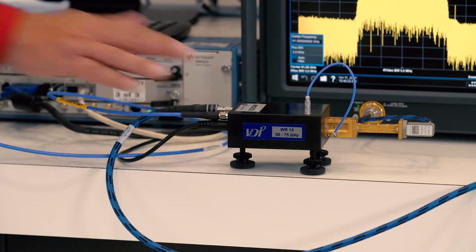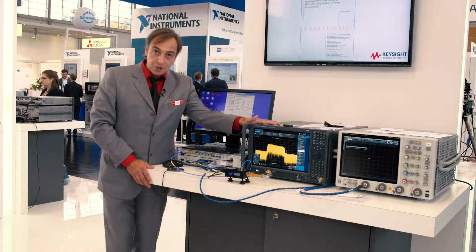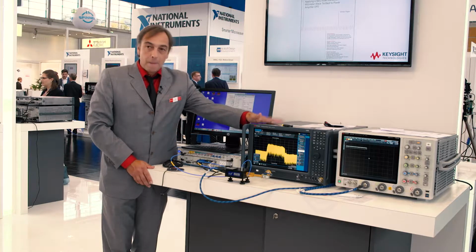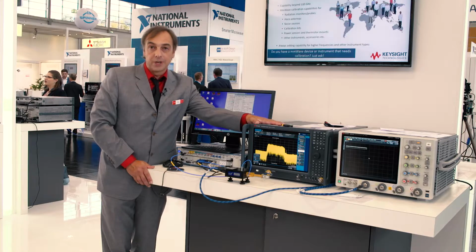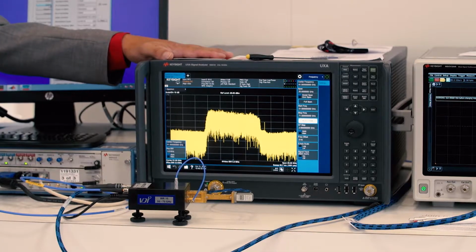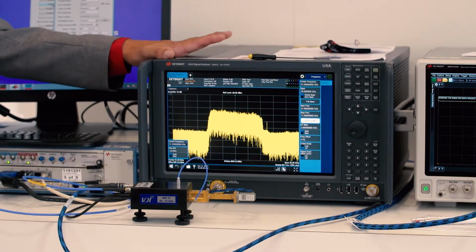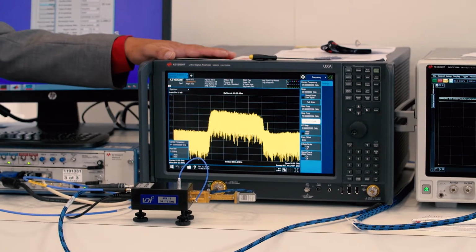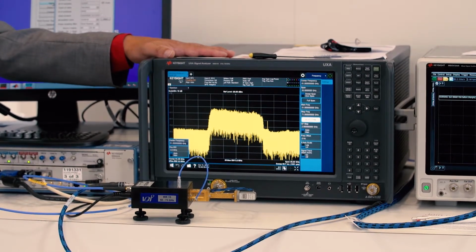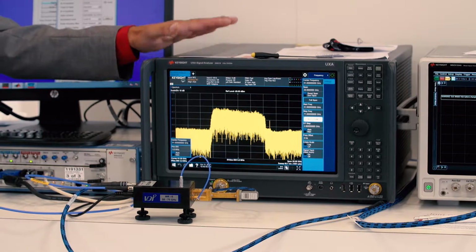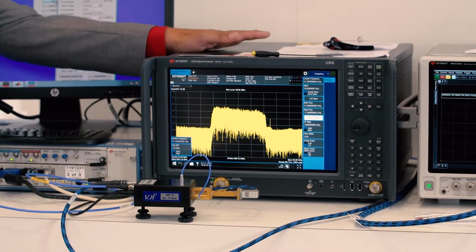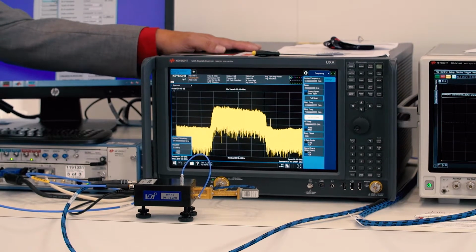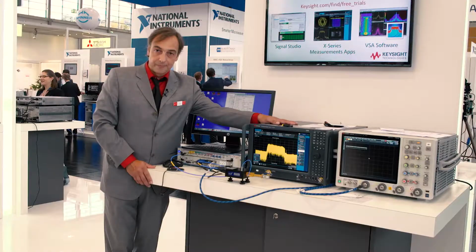The 61 gigahertz signal is captured on the analysis side by a spectrum analyzer that supports from 3 hertz all the way to 100 gigahertz. The spectrum analyzer would support 1 gigahertz of analysis bandwidth. Due to the wide bandwidth that we need in certain applications, it also has a specified IF output of 5 gigahertz.